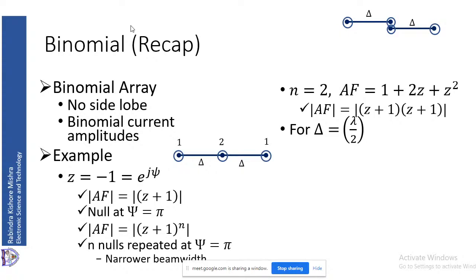So this is how we represented that. So three elements that we consider as four elements, each of amplitude 1. Now the top one you can take as a simple array of amplitude 1, 1. Second is also amplitude 1, 1, same amplitude. So it becomes a uniform array. Once it becomes a uniform array, you can find out what its pattern is. So for the first one, the pattern will be figure of 8, which will be exactly as if there is one source exactly between these two elements. Therefore that point will be at the center.